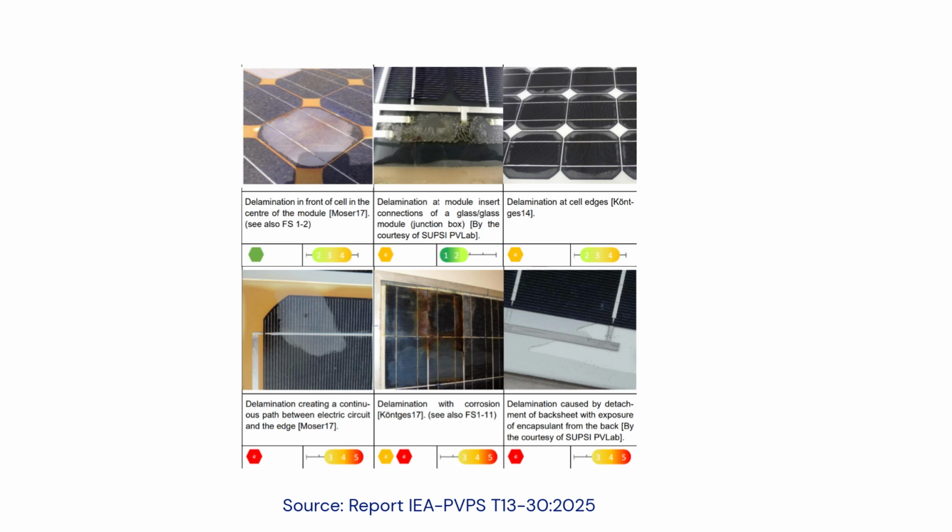The adhesion between the glass, encapsulant, active layers, and back layers can be compromised for many reasons. Typically, it is caused by the manufacturing process, like poor cross-linking of EVA, too short lamination times, too high pressure in the laminator, contaminations, improper cleaning of the glass, incompatibility of EVA with soldering flux, inadequate storage of the raw material, or environmental factors, like thermal stresses, external mechanical stresses, UV.